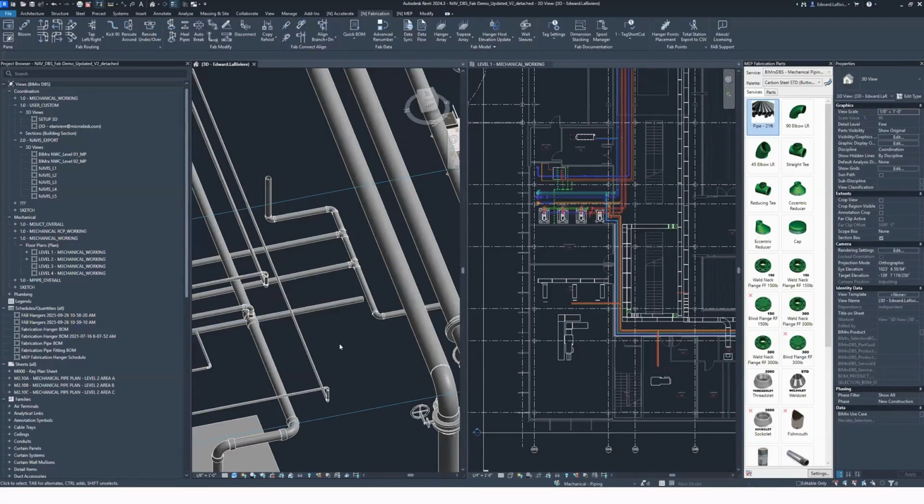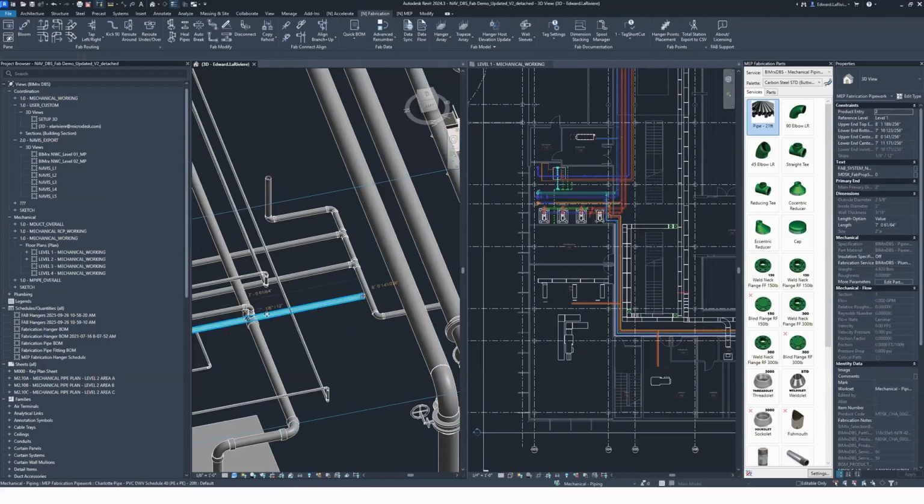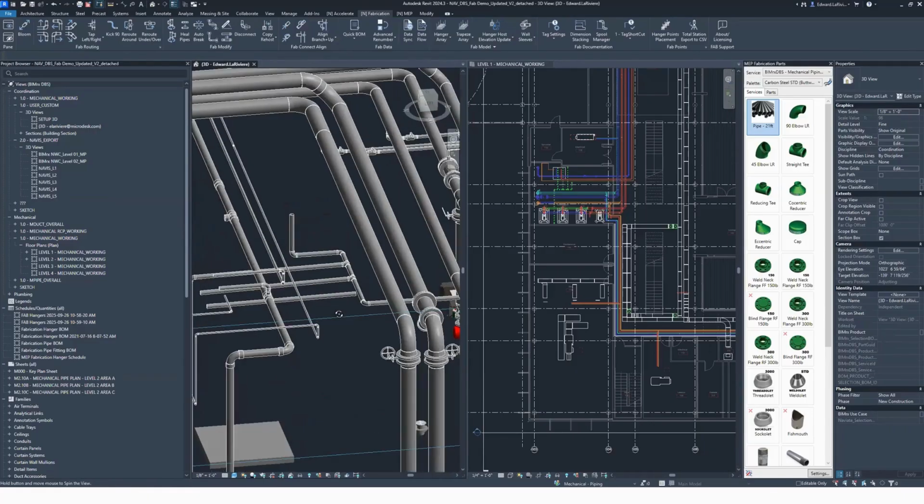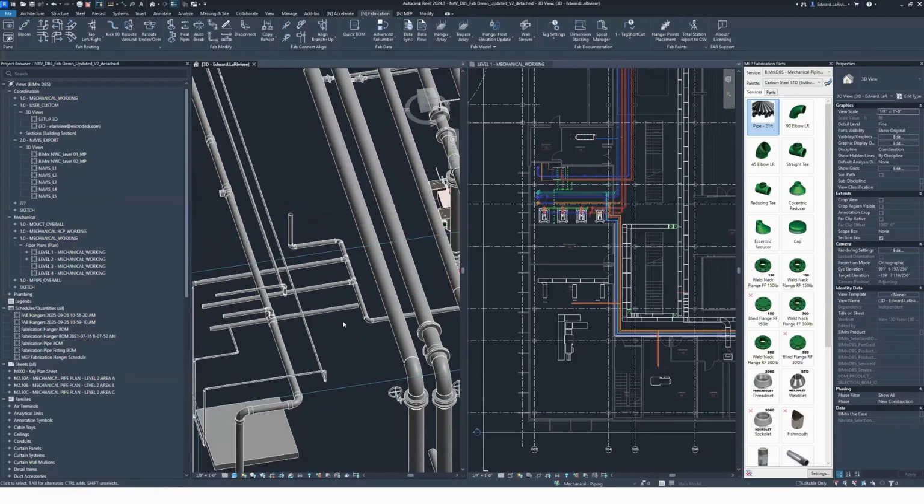I want to inherit that slope. This is a common modeling mistake as we start routing around. You just forget slope on one of those pipes and you notice it when it's time to finally connect them. So a nice big brother to that align branch tool, align branch plus, actually letting me jump in here and inherit that slope while I line these items up. But maybe I don't want a flat connection this time. Maybe I want a 45-degree connection.